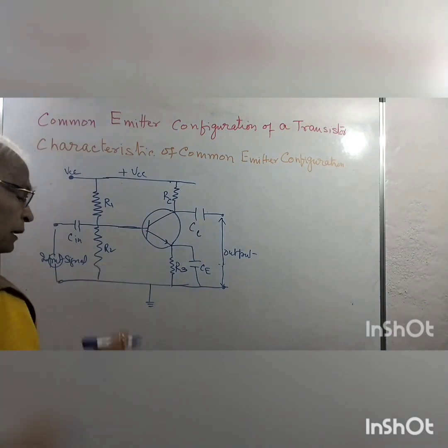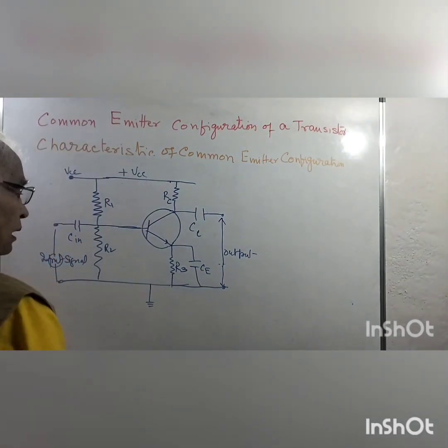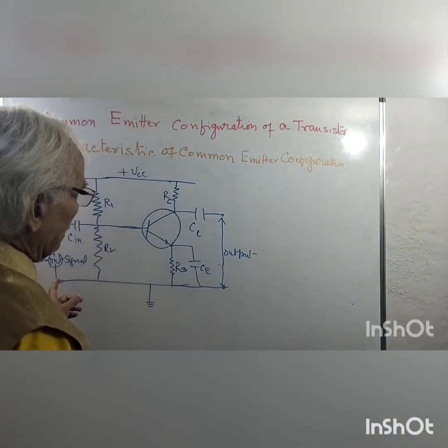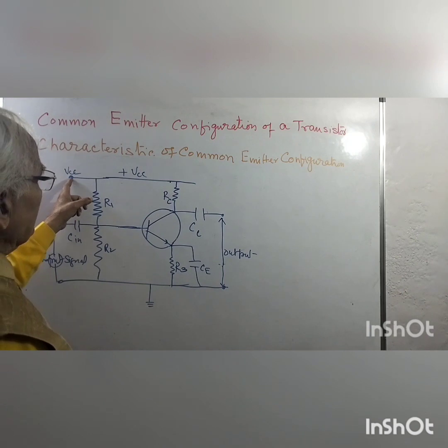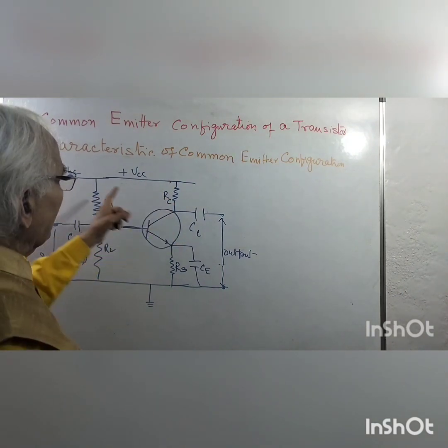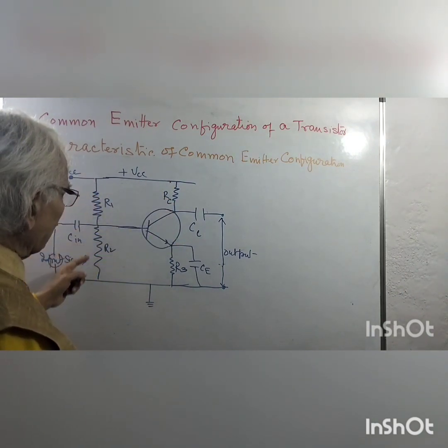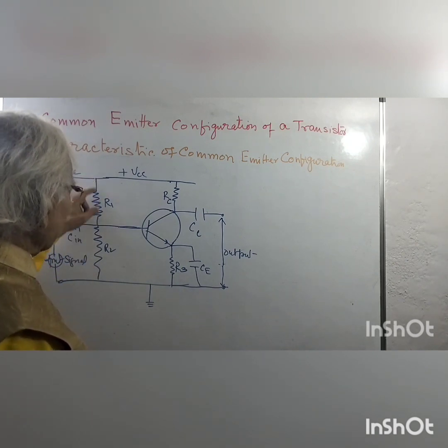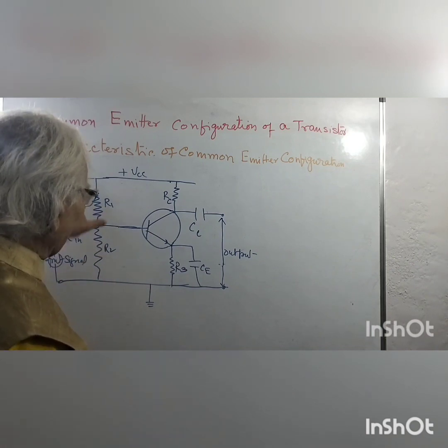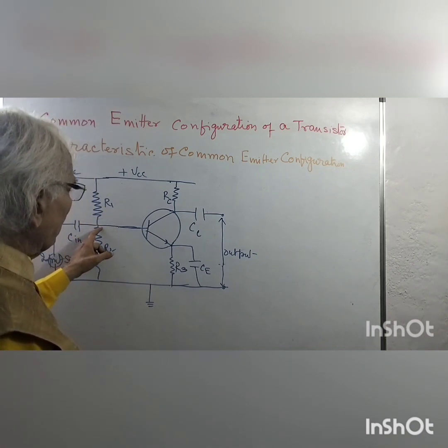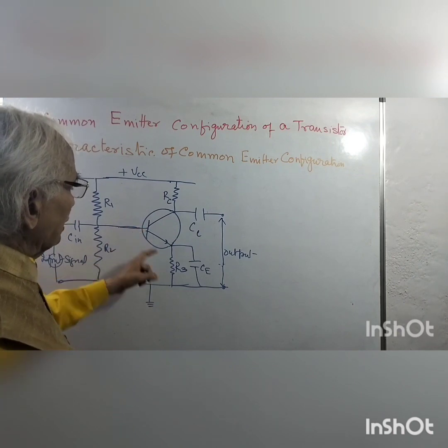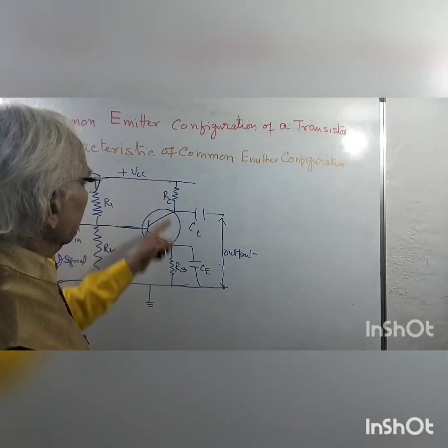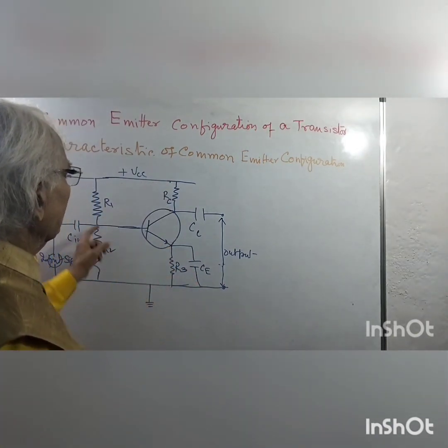So this is the circuit actually which is used where we don't use two batteries. Only one battery VCC gives the voltage to the collector, and using the resistance bleeder circuit here, series resistances, making a combination from here this voltage, and then this is the ground. So current flows here and produces a voltage drop here, and that is used for the biasing of the emitter and base. And this is the biasing for the collector and the emitter.